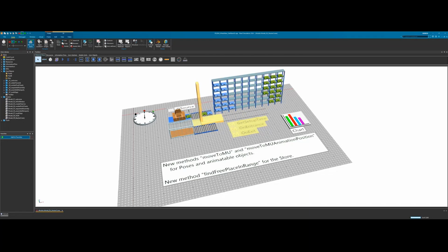So, of course, the behavior may be different, but it's no problem to open any old model. Well, I don't know about 100% any, but if it's like 20 years old, maybe you will run into some problems. But theoretically, yes, you can open any model that was saved in an older version in a newer version. The other way around is 100% not possible. So if you have saved your model in version 25.04, you can absolutely not open it in any previous version, for obvious reasons.